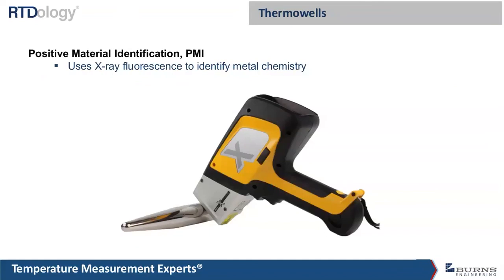And given no information or heat numbers about the well, we can use a device that uses X-ray fluorescence to identify what the material is. It's not going to give the exact chemistry of the material, but it will tell us whether it's like 316 stainless or maybe one of the more exotic alloys like Hastelloy or, you know, Al6XN, for example. So that's another way to do that. Typically just called positive material identification, or PMI.